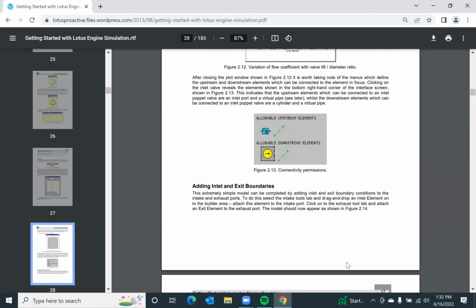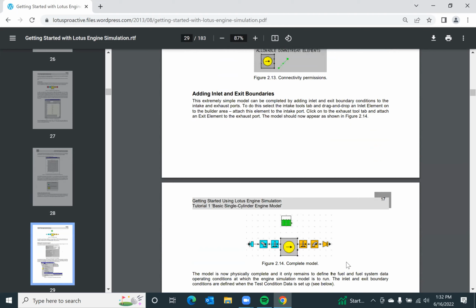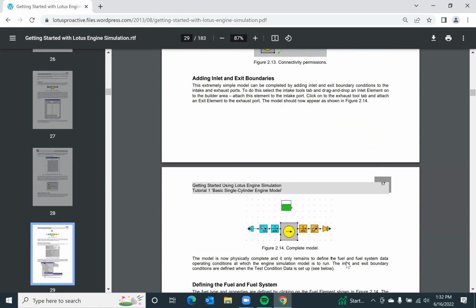Then what you do is you have the intake plenum, where air and fuel get mixed. Earlier, we used to have a carburetor, wherein the air would come and the fuel would get atomized, just like the misting system that we see, and that air-fuel mixture would get fed into the cylinder.